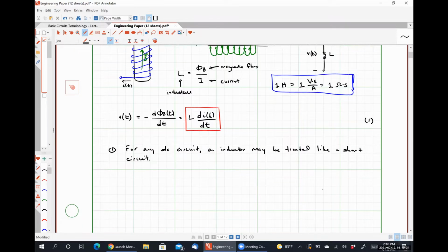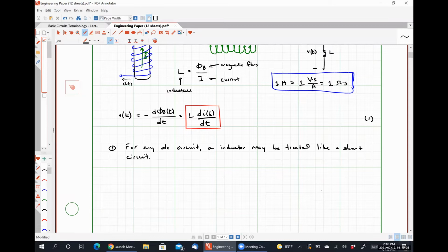All right. So if we take equation 1, oh, sorry, we have a second thing to look at here. My apologies. Another thing that we can observe is that the current flowing through the inductor cannot change abruptly, right? Effectively, that di by dt term cannot approach infinity because that will give us an infinitely large voltage, which infers that we are having an infinitely large transfer of energy in an infinitely small amount of time, which obviously cannot occur.